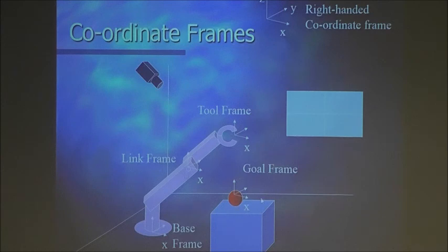Having a goal like this, a specific XY coordinate of this red ball, how much each of those 6 joints have to move to get there exactly. That's the inverse kinematic problem. Okay? And that has a problem which has an infinite solution. You'll see later. But you have to choose the right one.